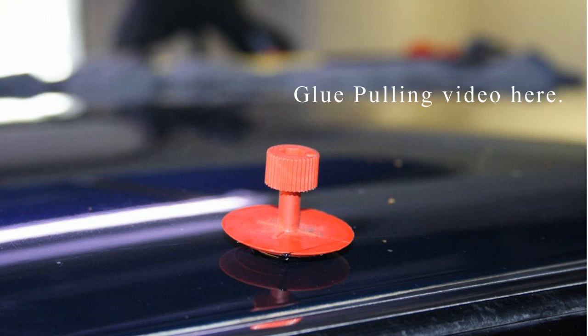Next we will talk about glue pulling. This method is used particularly on dents situated on areas such as roof rails, double-walled areas on sunroofs, on hoods near the windshield, or any other spot with limited access to the back side of the panel.